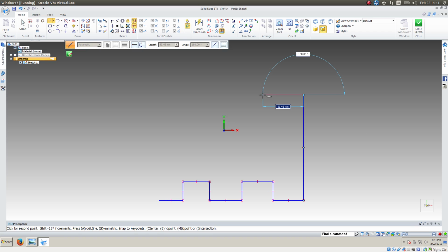The thing to think about with all these helps it's doing is that it's drawn that way, but the constraints aren't necessarily added. So these vertical lines here and horizontal there show that these are horizontal and vertical lines. So those constraints are added. But I also made it so that this endpoint was at the same height as this endpoint. You could see that dashed red line that was there when I was drawing, but that constraint didn't get applied. It just drew it at that length. So just because it's shown at that length doesn't mean it's constrained to be that length.